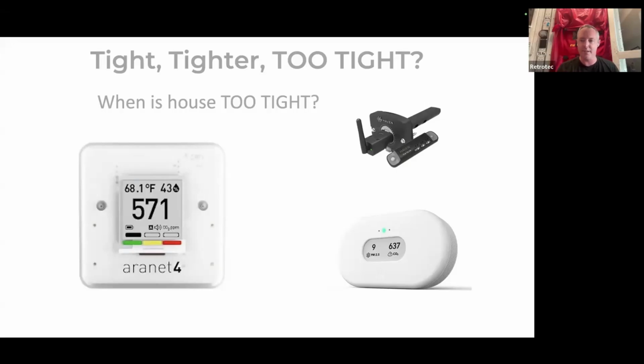But really, it's like, okay, when do I need to think about ventilation? We'll just measure and see what you have first, and see what happens. But again, in my opinion, we need to really think about mechanical ventilation for every building, but especially as we get tight, it becomes more important. And again, the answer to the question of how tight is too tight is that there's no number for that. You can get it as tight as you possibly can. The more the merrier. And then put in a plan for something like this to make sure that your air stays clean, and measure it.